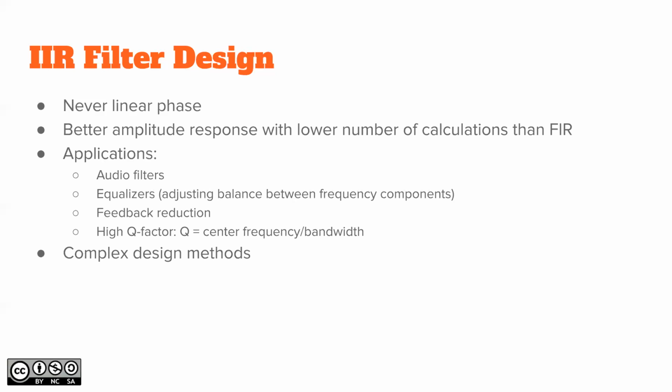But IIR filters are the most cost efficient, with a much better amplitude response with a lower number of calculations than a similar FIR filter. So applications, well, basically almost everything. Audio filters, equalizers, feedback reduction, high Q factor. An IIR filter, when you take a look at it, is actually a feedback control loop.